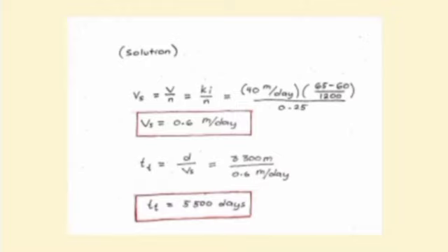First, we are required to find the seepage velocity. Since we are dealing with confined aquifer, we can say that seepage velocity is equal to actual velocity. And we have a formula for actual velocity. Actual velocity is equal to velocity of water over porosity. But according to Darcy's law, velocity of water is also equal to Ki, where K is the hydraulic conductivity and i is the hydraulic gradient. So we have now a new formula for actual velocity.